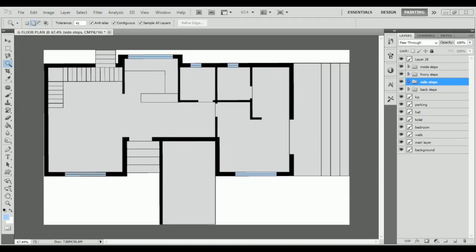Now, what we have done is we spent time in the last topic creating all the layers, right? So creating the layers is very important because if we don't have a layer, then we really can't give any layer style to it. So let's see how we now edit each and every layer to provide a particular material, right? So we're going to use the move tool over here, guys, and I'm just going to select from here directly whichever one we want to start with.